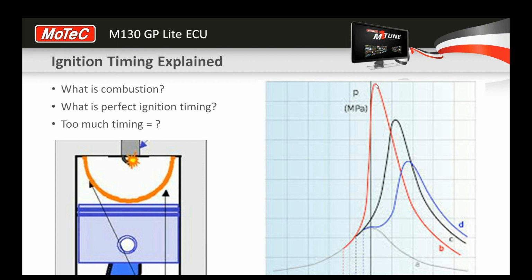definitely would put the peak cylinder pressure on the other side of top dead center. We could easily do some damage, blow a head gasket. Potentially, if it's a performance engine, we could damage a piston, bend a rod, all sorts of things. So too much timing is not a good thing. Even if detonation isn't occurring, if you have a very good quality fuel, just adding ignition timing randomly is not the way to go.